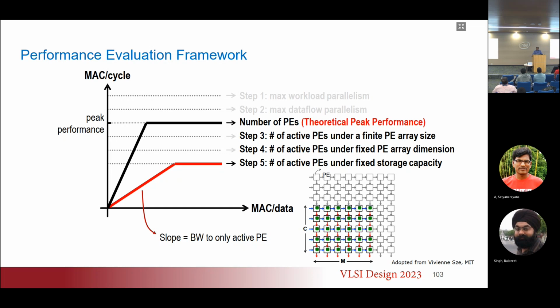By banking it, by partitioning it, so that my last level cache is partitioned into, let's say, 8 blocks, so that I can do 8 reads or writes, right? And if I wanted to do 100 reads, I'll have to bank it by at least 128. And when I start banking by 128, I suddenly have a real issue with the number of interconnects I'm going to have, and if they're all going to be in the chip, the amount of the layout and the routing complexity I'm going to have, I'll immediately have to start thinking about where to put these banks.